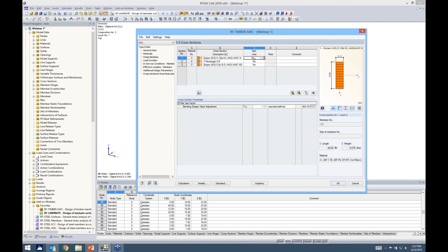Now you can choose to optimize these members. Let's say we're well below 1 or maybe we're above 1. We can optimize. We get that question quite a bit, and that's certainly an option in these add-on modules. So you can optimize from the current row, which means it will choose one of the glulam Western species, or we can choose from our USA favorites list that I showed you before.